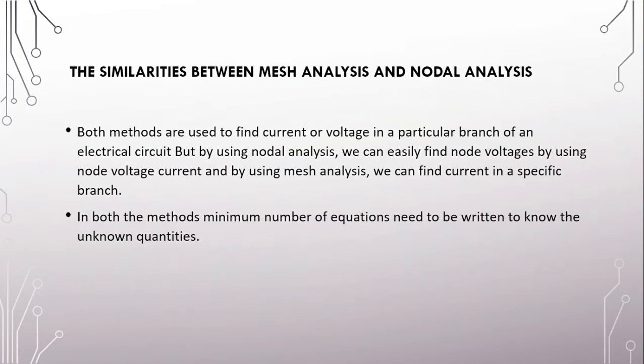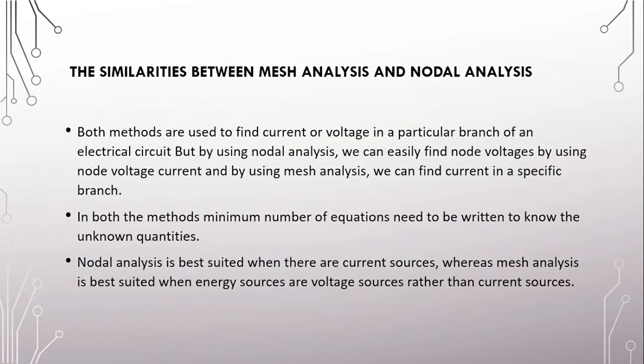In both methods, the minimum number of equations needs to be written to find the unknown quantities. Nodal analysis is best suited when there are current sources, whereas mesh analysis is best suited when the energy sources are voltage sources rather than current sources.